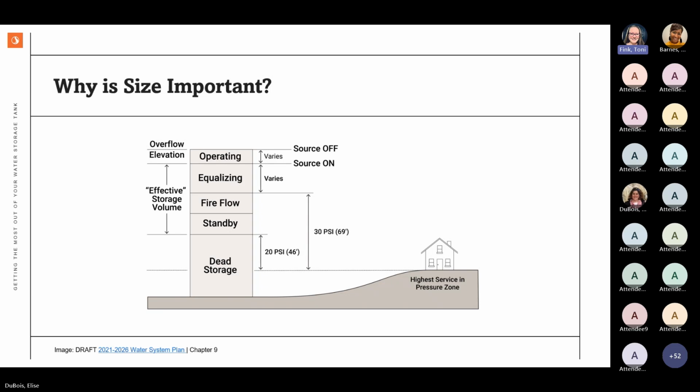Would strategically placing the mixers in the tank reduce the stagnation, sediment, and biofilm? Yes, it does. If we place them correctly, if we do a CFD model to ensure that they're really placed correctly, it helps to reduce all of that. Clients with mixers tell us all the time that they've had to order less hypo, or they're having higher disinfectant residuals than they thought they would get. Like they're exceeding what we normally used to see. And that's part of the reason for having mixers.